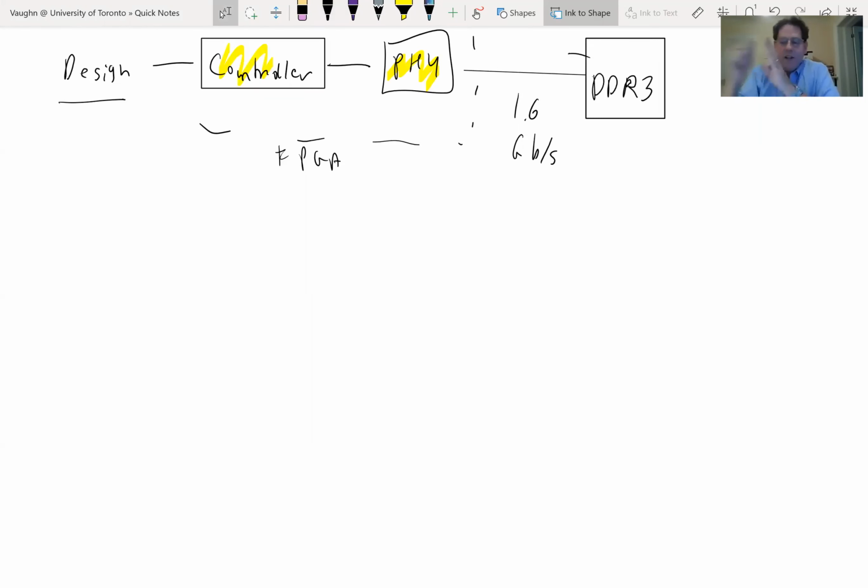I'm kind of digressing a little bit, but there are some interesting aspects to this interface protocol too. This is called the source synchronous interface protocol. That's basically one of the two ways you do high-speed I/O. Source synchronous means you send the clock beside the data. The other way you can do it is with serial I/O, which we'll talk about a little later in the course when we get to some examples of those blocks.